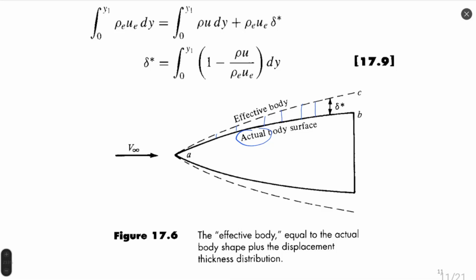But relatively simply and quickly we can calculate flow while taking into account the curvature of flow due to the presence of the boundary layer. So this is calculation of viscous effects without calculation of the boundary layer, a kind of compromise between accuracy in physical simulation and performance of this calculation.